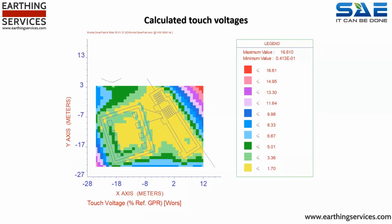This plot indicates the calculated touch potential in the event of an earth fault. The plot below is based on a percentage of the EPR, being 5.01% of 413 volts equals 20.01 volts, which is within the limits as indicated previously.